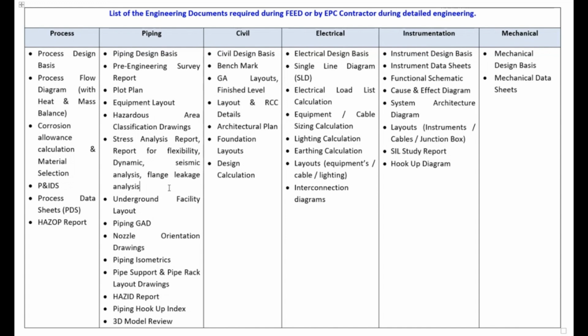You have already considered extra supports for that piping, you have considered shock absorbers in between, you have considered flexible joints in a way that, if the vibrations are more, will address it. So all these things will help you analyze that your compressor and piping relationship remains smooth without any trouble for the lifetime, the design life of 20 years or 25 years. So these stress analysis reports and all these things are mandated. Okay, then